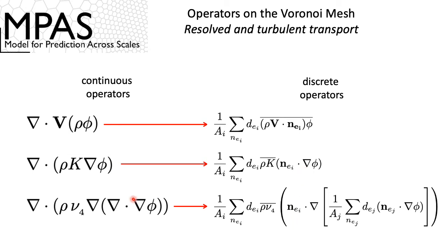And what you see here is we've just taken this mixing ratio phi and applied this operator again to get you here. So if you look at the second order operator, we've just repeated it down here, but we've pulled out the turbulent velocity and replaced it with this turbulent velocity out here.